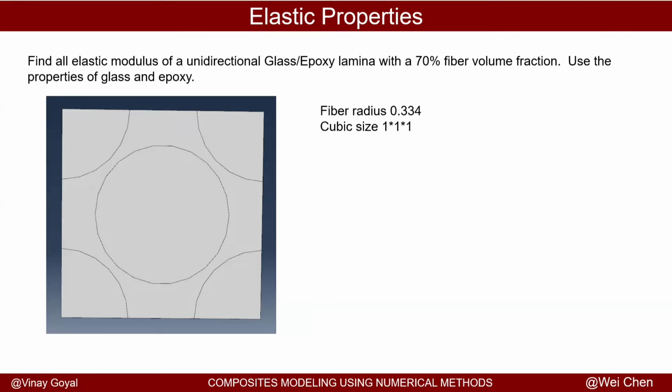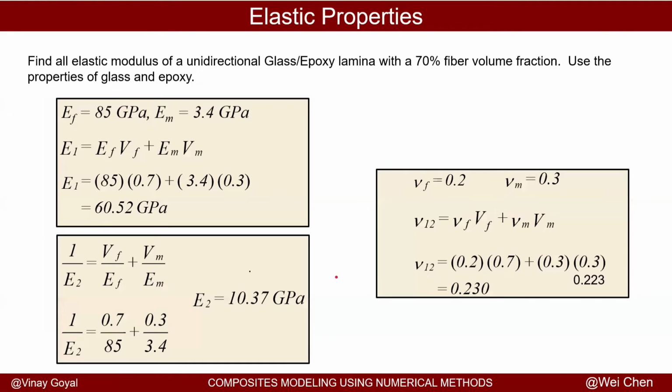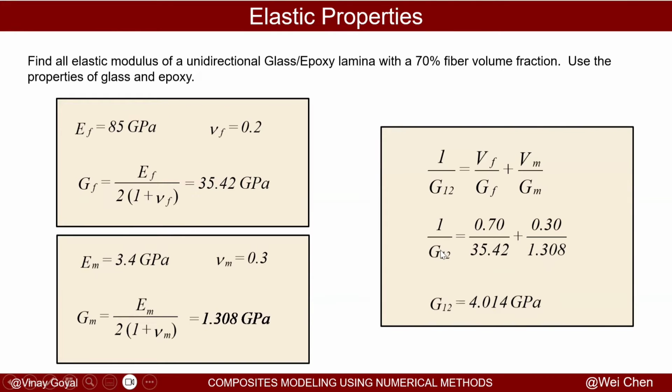The good news is that properties such as the E11, the modulus in the one direction of the composite, the modulus in the second direction, the Poisson ratio, and shear modulus, can all be found through either testing that has been done historically or through testing that you do as a support of a program.